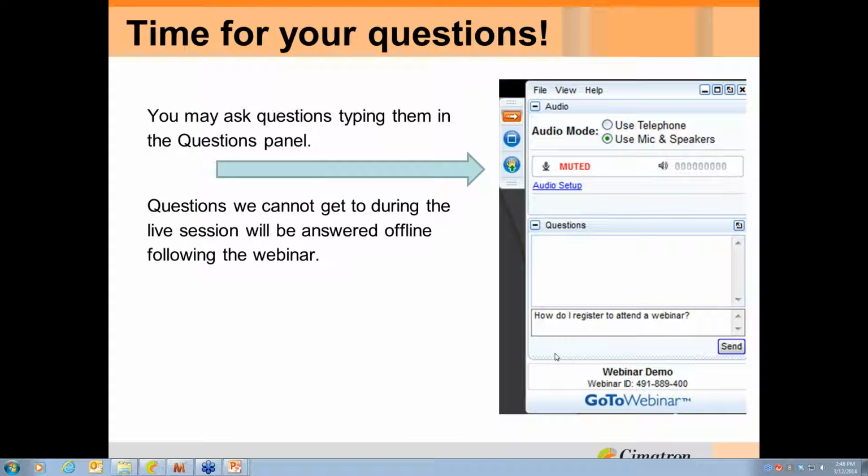What if I use a catalog part that is different from what Cimatron provides? Can I just use one from the manufacturer? Yes, although the catalogs, as you saw, have some rules built into them. So in order for all that to work, you will have to do a little work on the part and prep it for Cimatron. Like I mentioned, we do have a lot of catalogs, but some of our users do change them a little bit if they need something specific. So again, not a problem, and well-built catalog parts are the biggest help in getting some of this to work the way you want it to.